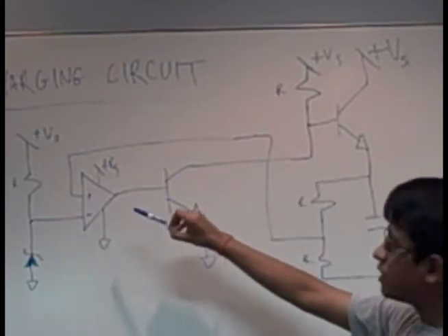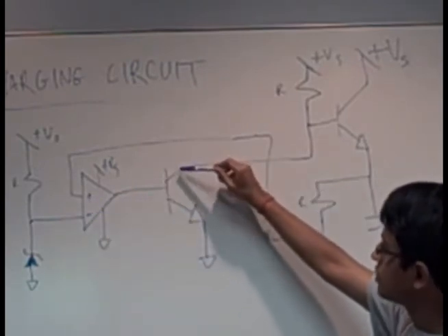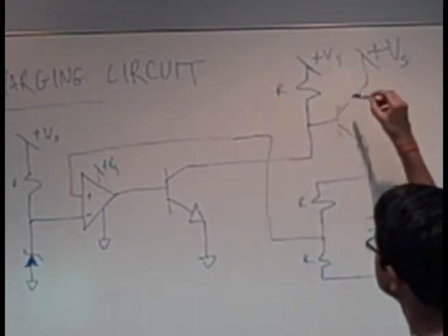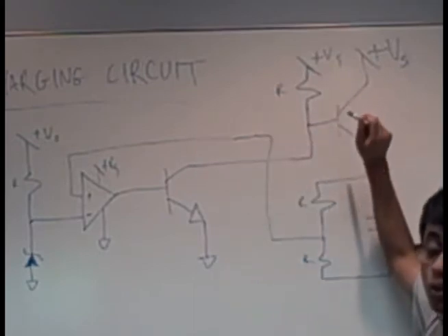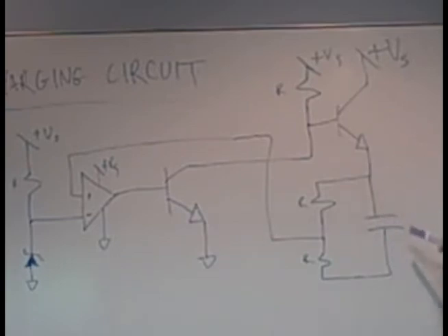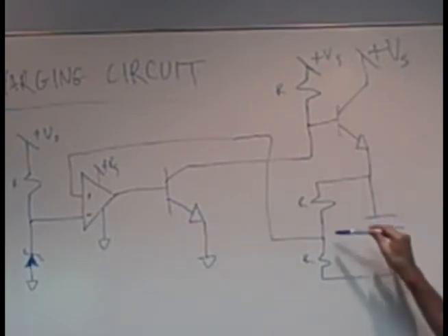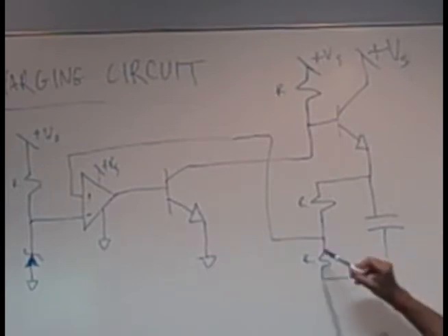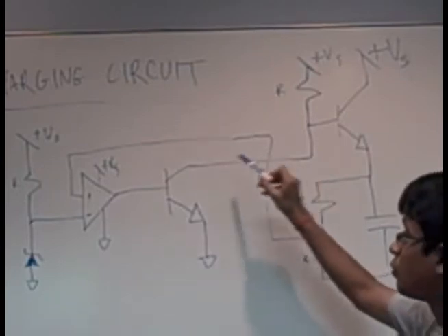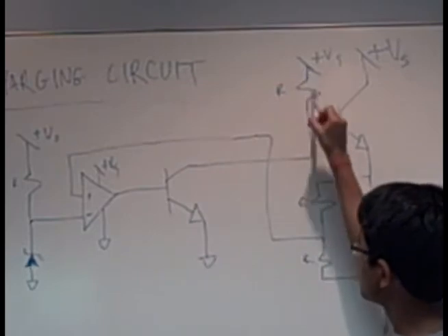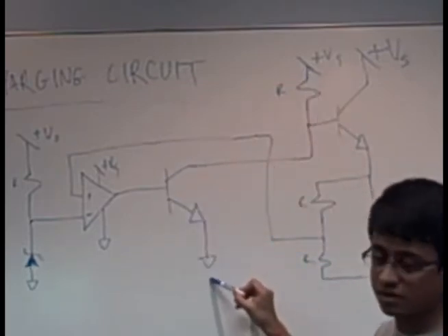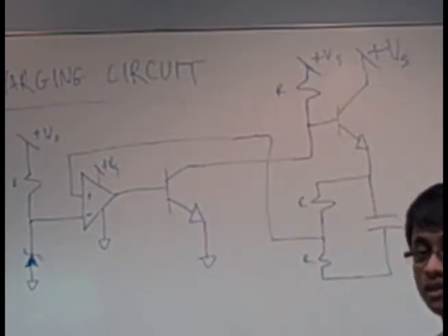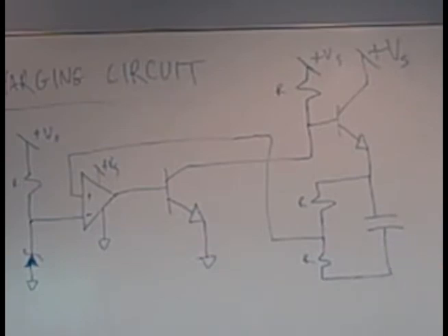Once the flow is available, it turns on this transistor, which then tells this transistor to turn off. Once this is off, it stops flow to the capacitor. Since this is a voltage divider, we assume that the voltage at the capacitor is 5, since we get a flow of 2.5. Once we get a flow of 2.5, we just allow flow straight from the capacitor down to the rest of our circuit. And thus, the capacitor is never driven beyond 5 volts, and once it reaches 5 volts, the charging is stopped.